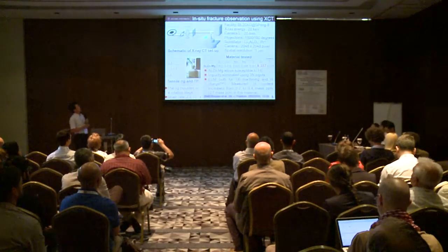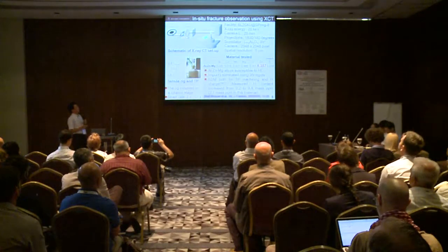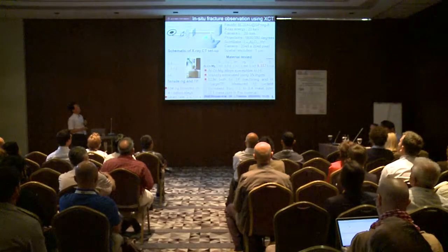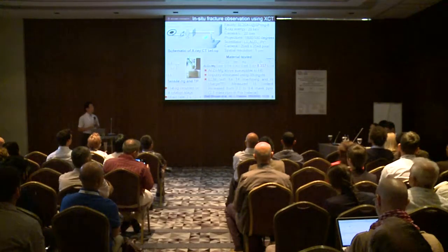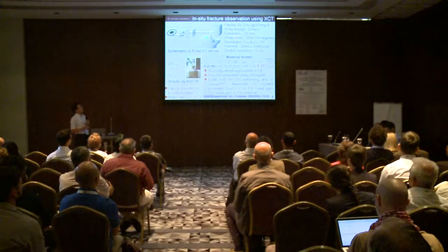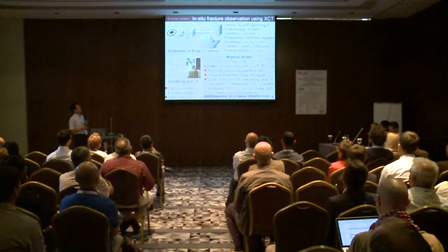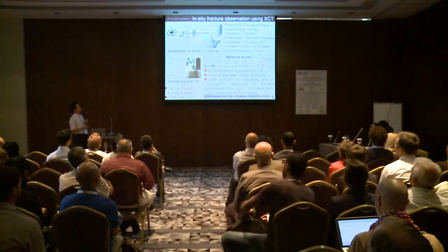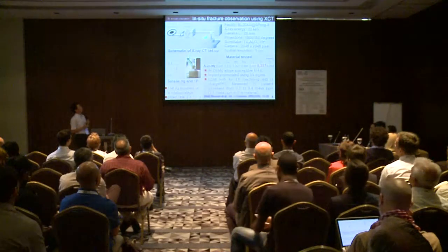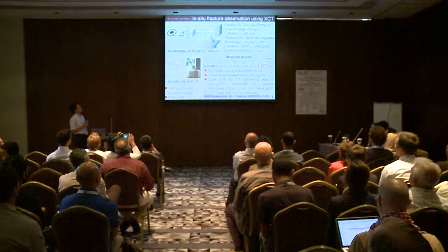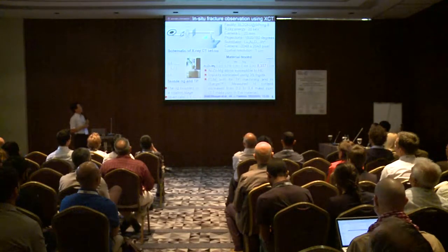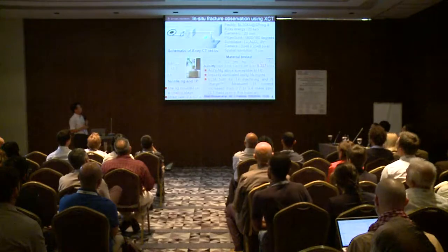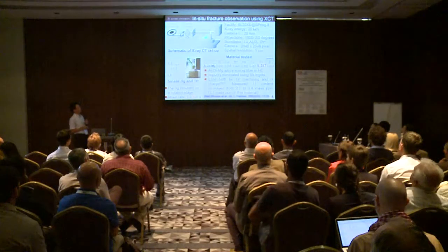Fundamentally, we have used simple projection-type X-ray tomography at the high-resolution 3D imaging beamline of the Japanese synchrotron radiation facility called SPring-8. We adjusted the experimental conditions to obtain a very high spatial resolution of about 1 micron, which is fairly close to the physical limit of this technique. We mounted a specially designed tensile test rig onto the rotation stage of the tomography setup to make in situ observations of a tensile test, which is not as specialized as something like SSRT, because its strain rate is just 10⁻³ or so.